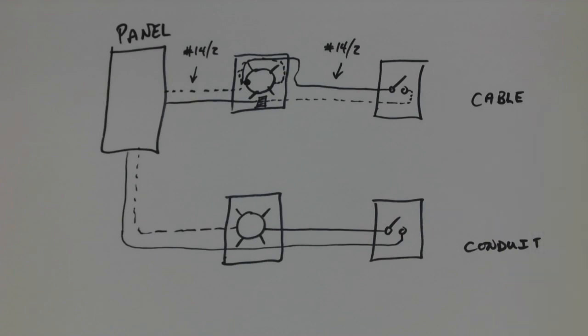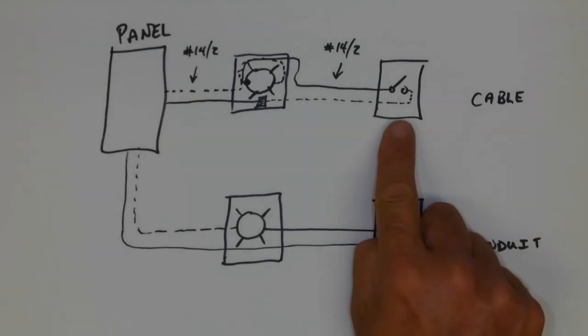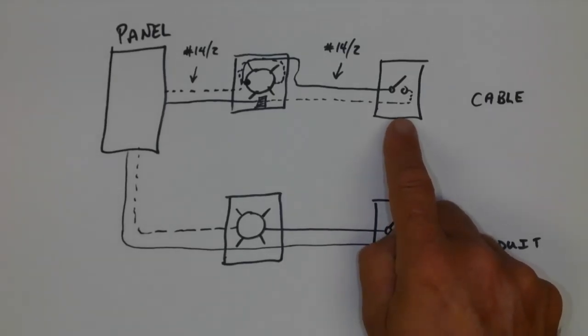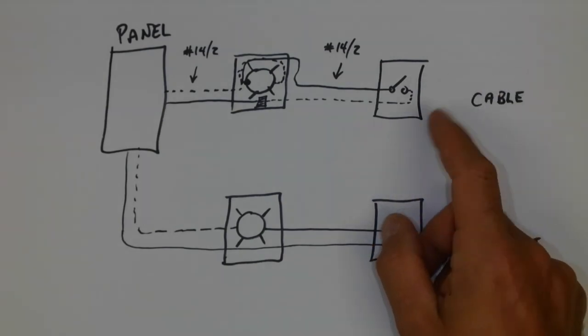The reason that we would have done these in the past is that we could have put in a much smaller box at this point. And sometimes in older installations, there was something called a door jamb switch where you open the door and the switch turned on a light in a pantry. That door jamb switch was exceedingly small. It wasn't a light switch you would flick on and off with your finger.